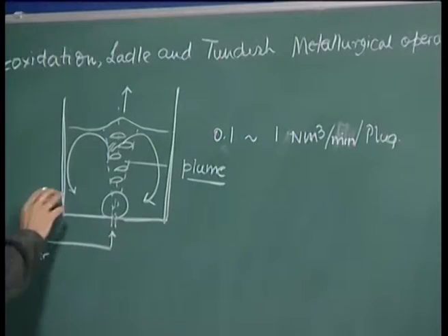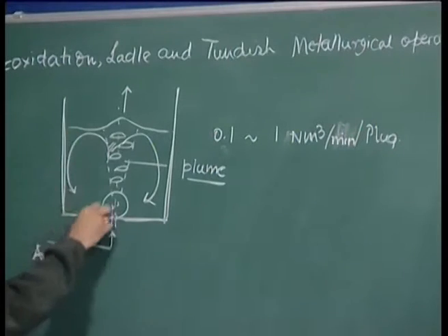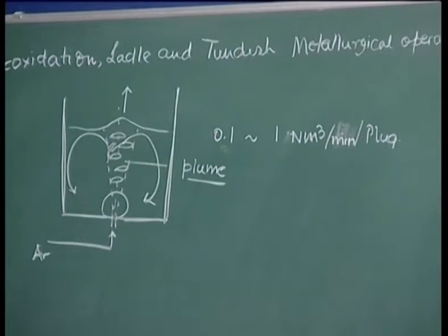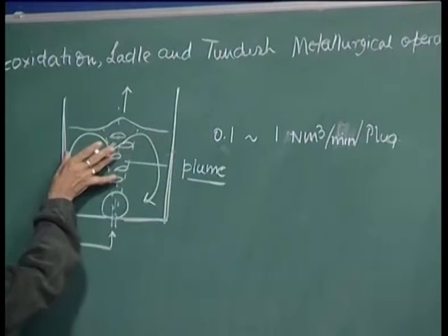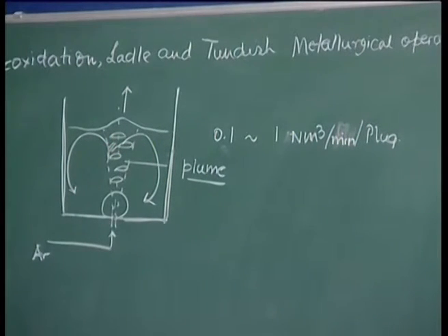And it is well known that this moving molten steel helps in homogenization of the bath in terms of its chemical composition and its temperature, and it aids in inclusion agglomeration. Depending on the position of the nozzle, whether it is too closely located to the wall or not, it can also create some preferential refractory wear, particularly in the vicinity of the rising plume. In this case, of course, it is not significant because it is going to be equidistant from both the walls.